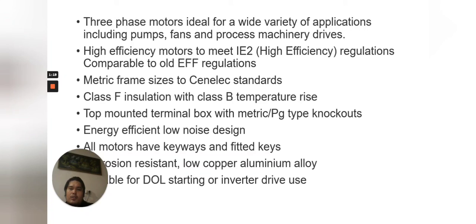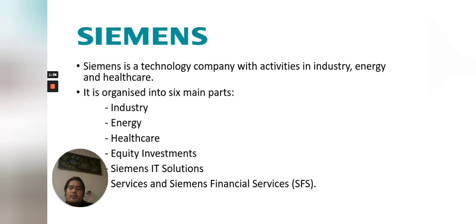Top mounted terminal box with metric type knockouts. Energy efficient low noise design. All motors have keyway and fitted key. Corrosion resistant low copper aluminum alloy. Suitable for direct online starting or inverter drive use.